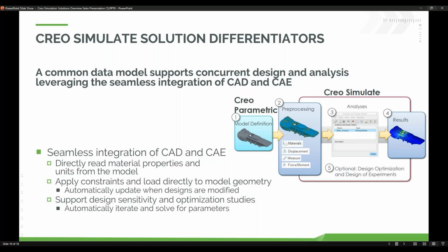If I change the width of that diving board from, let's say, 24 inches to 25 inches, that's going to have a minimal effect on the deflection of the diving board. It'll have a little, but not a lot, because we still have our same cross-sectional depth, although it is a little bit wider. But if I change the thickness of that diving board from 2 inches thick to 1 inch thick, that's going to have a drastic effect on the deflection of the diving board.